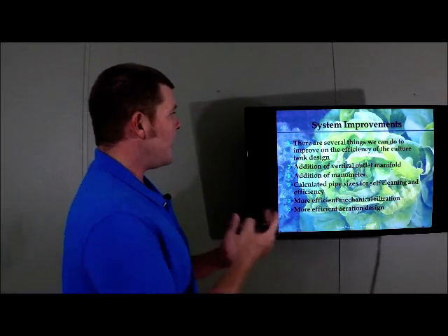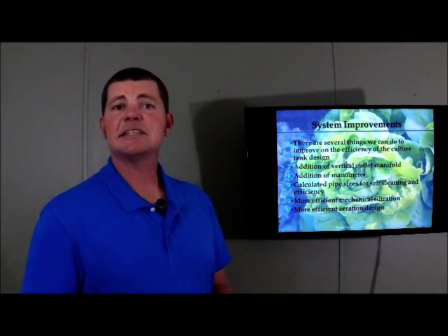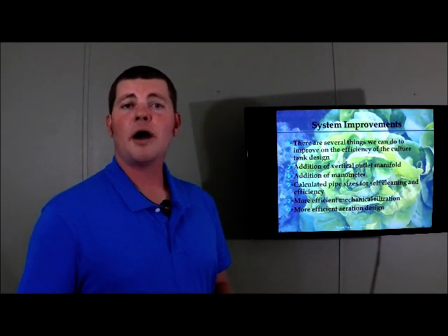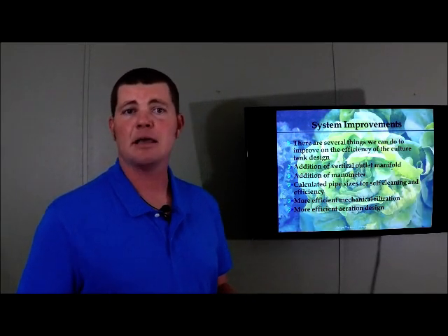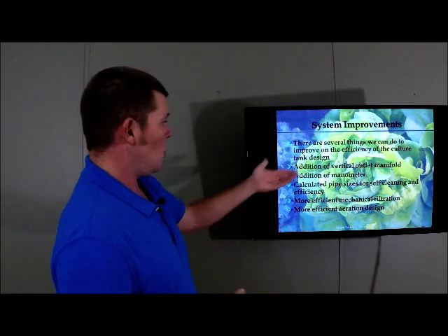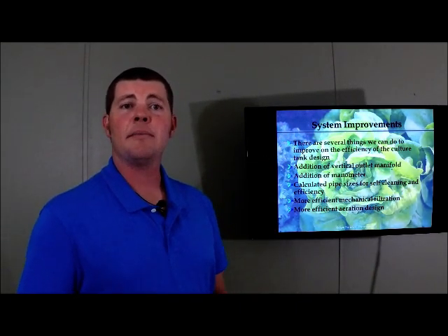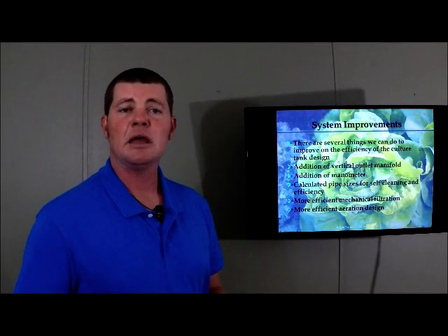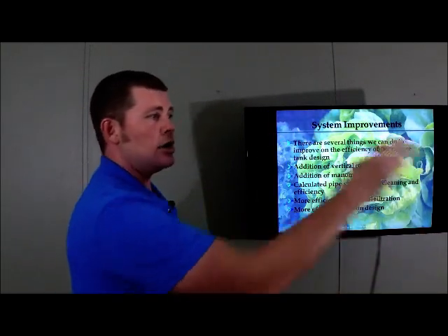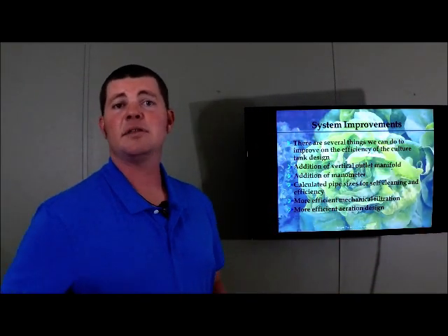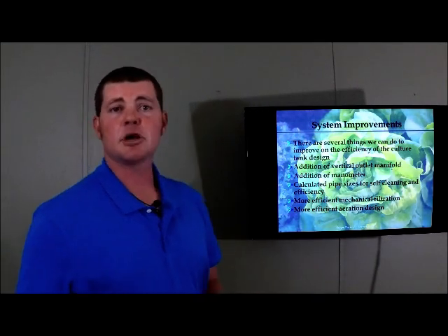Well, without actually having a flow meter or a manometer, you're just guessing as to how much water you're putting into each one of those tanks, unless you take a physical measurement with a 5-gallon bucket or something like that. So a quick little addition of a clear manometer sight tube would actually allow them to adjust those levels perfectly to say, we want 70% of the water going here, 20% here, 10 and 5, or whatever they decide. But they could do it all by this clear sight tube, which we'll get into the construction of shortly.